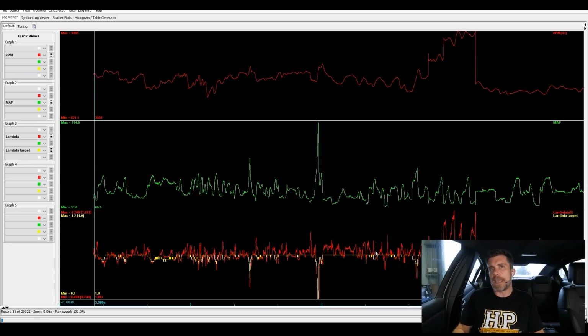It'd be very different if we had just looked at, for example, a single ramp run on the dyno. There would have all of the data that we really need. But here we're looking at multiple instances of the same situation in terms of manifold pressure and engine RPM. And of course, when we're looking at our fuel map in a speed density system, that's what we're mapped off. So if we're looking at the same instances time and time again, let's say 3000 RPM and 85 kPa, and we've got maybe 100 different samples through this entire file, it's really difficult to see a trend.